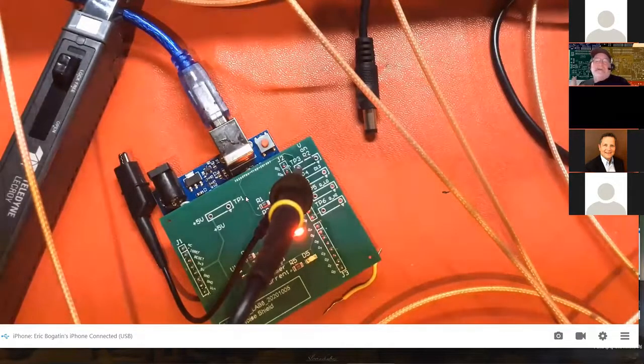So if you've got a 10 megahertz bandwidth signal, then who cares, anything will work. But if you're pushing the limit and you get a couple 100 megahertz bandwidth signal, then you want to do everything you can to reduce the discontinuities, make a clean path so that your probe has a bandwidth at least twice the bandwidth of that signal.